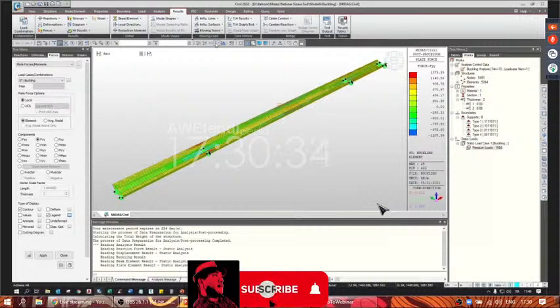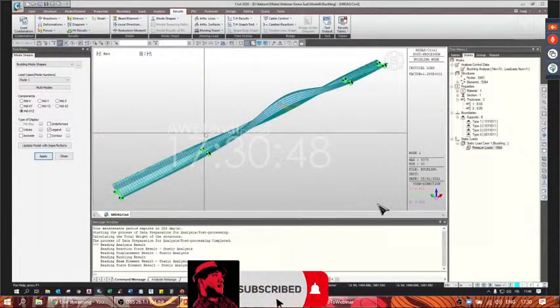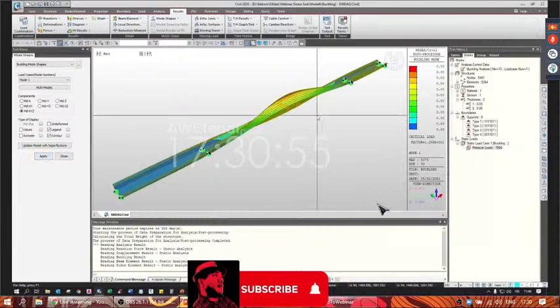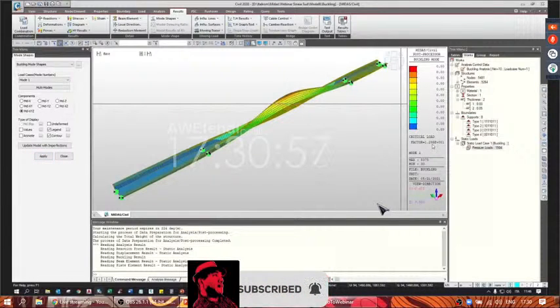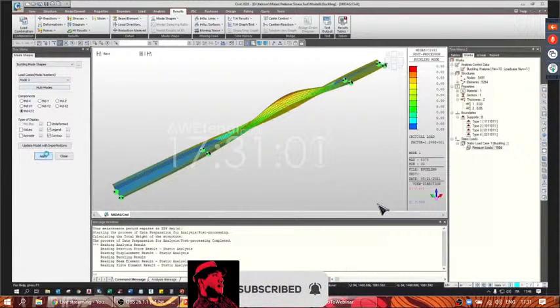we have to multiply it by the critical load factor that we can find in the buckling mode shapes. Here we have each mode analyzed. We can see different ones. Okay, this is the first one. On the right, we can see the critical load factor for this mode, and also we have the next modes.